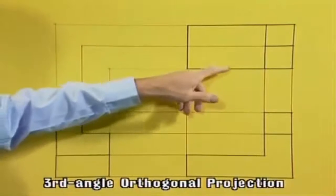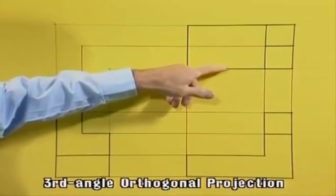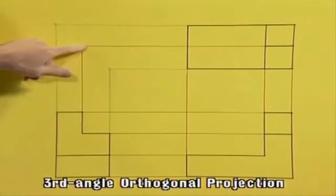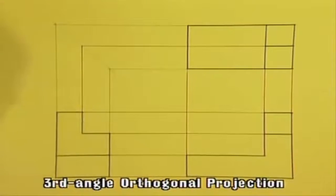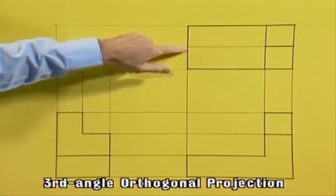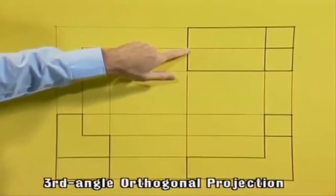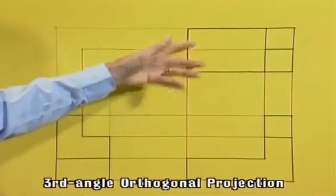Any other details we need to transfer from one view to the next, we just transfer along, hit the 45-degree line and drop down, or vice versa. In this particular case, we've only got one piece of detail, so it hardly seems worth setting the projection system up. But in most technical drawings, there will be a host of detail that we'd want to transfer across.